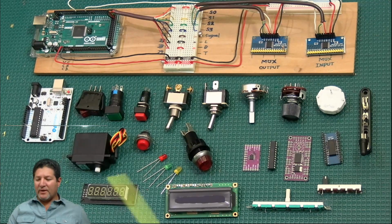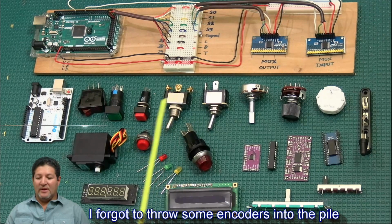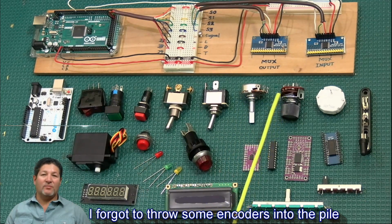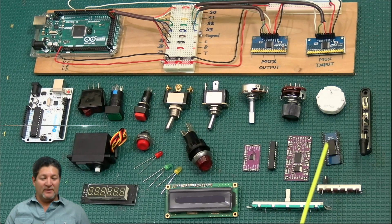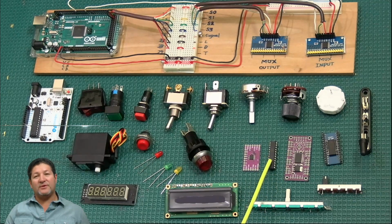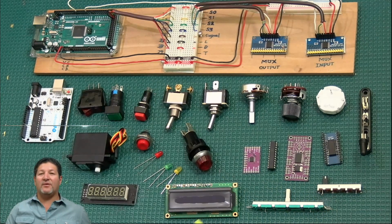We can connect, for example, toggle switches, like this or like these right here. This is just a basic 2 position. This is a 3. You can connect push buttons, or you can connect LEDs, potentiometers, rotary switches with multiple positions, stepper motors. These are steppers, and then the VID 6606 stepper driver. You can do pulse width modulated devices with this chip right here. You can do the DM13A, for LED lights. This is a shift register, I think it's a 74HC595 or something. LCD screens, 7-segment displays, servos, and this is some other type of potentiometers, sliding potentiometers. And then there's some other stuff that I don't even own, that I don't have here. But there's a wide variety of things that we can connect to our Arduinos.